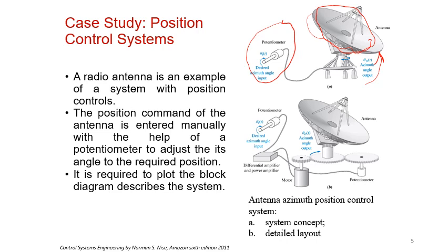Right now, we will convert this system to a system with parts. I mean, all the parts of the system are going to be here. So this is the control, where the input, the preset value, is sent to an amplifier, which is going to control the main motor, which controls the antenna. So the main motor will operate to rotate the antenna. Then the position of the antenna is measured by this kind of sensor. And the signal from the sensor is going to go to the amplifier to do the comparison and decide whether to stop or not to stop.